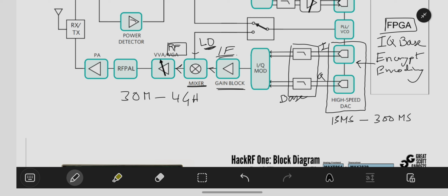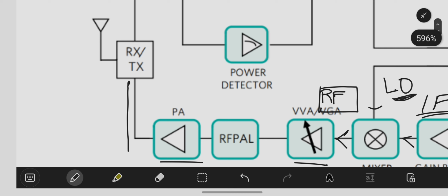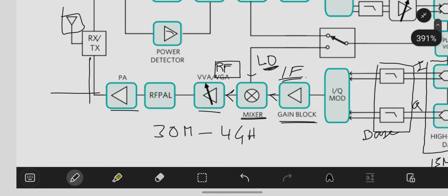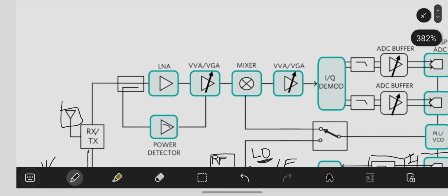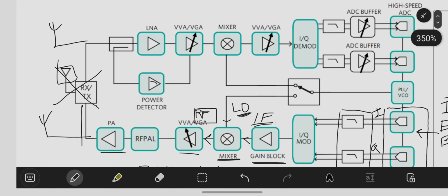Now once we get the modulated RF signal, we can do further signal conditioning and then feed it to, in this case, an RF switch. Now the RF switch can connect the single antenna, which we have here. We can also, by the way, use two antennas on the receive and transmit section and completely eliminate the need for this RF switch.